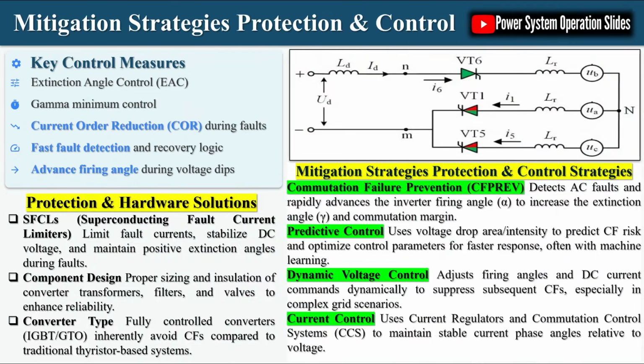Dynamic reactive support is essential, multi-in-feed interaction must be studied carefully, and operator training and fast protection coordination matter significantly. For system operators working with HVDC facilities, several practical recommendations emerge from the technical understanding of commutation failure.